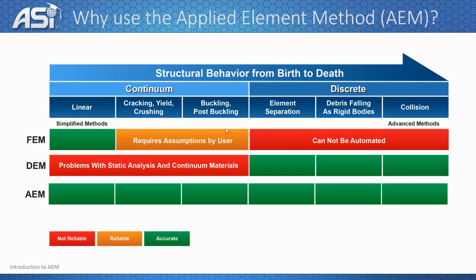For example, you put the end offsets and their rigidity. You also have to assign the locations of the plastic hinges. And finally, you have to account for the rigidity of the connections.